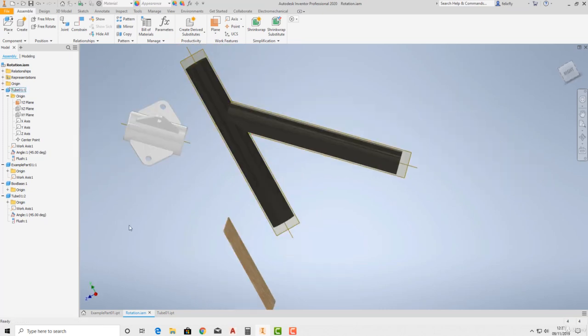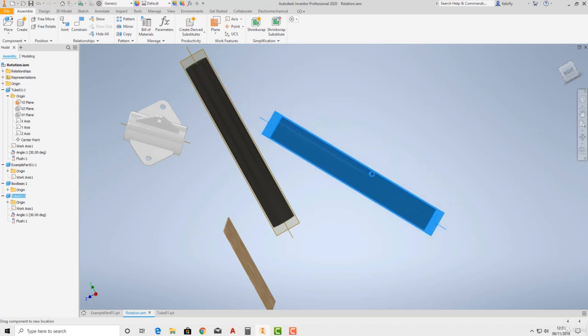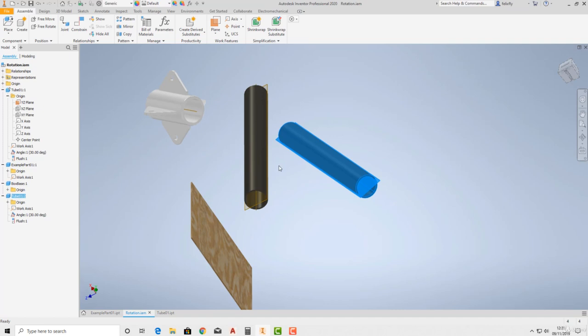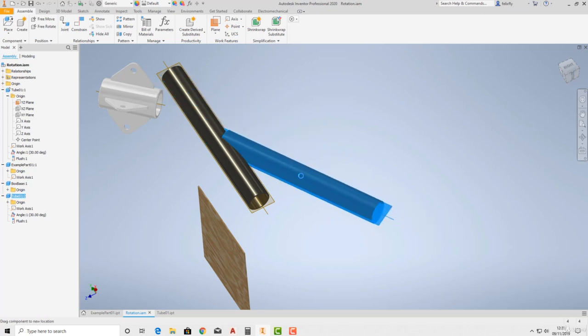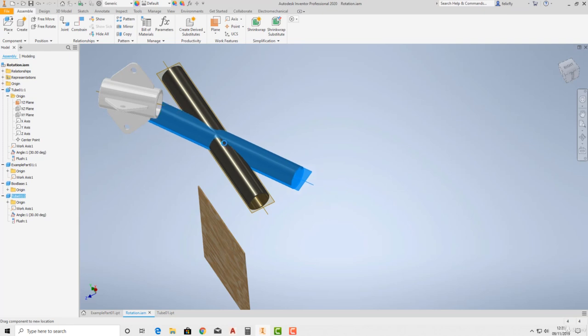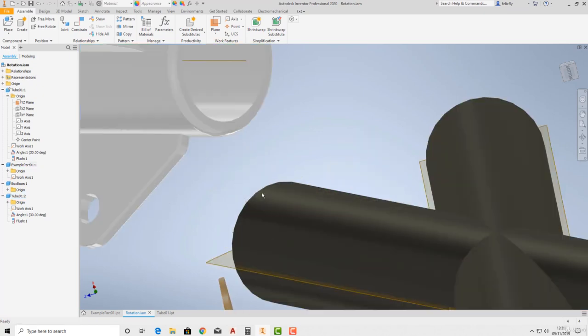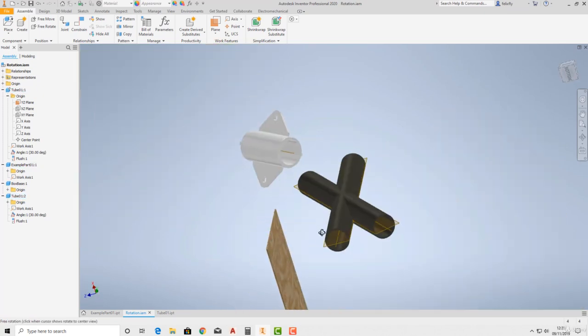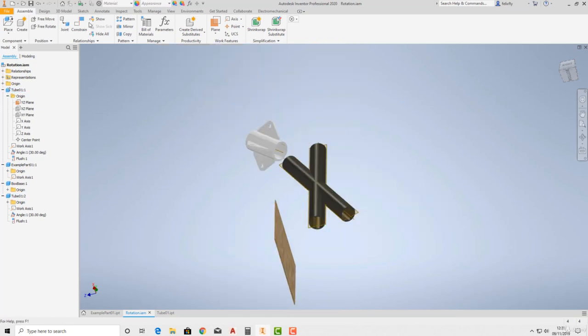Okay, so we'll just look at it from here to see it taking effect. So maybe you want that to be 30. Okay, and you can see it's now 30. You would need another degree, something else to fix it to get this orientation and everything, but hopefully you can see from that how the angular constraint works. We've angled these two axes. Okay,